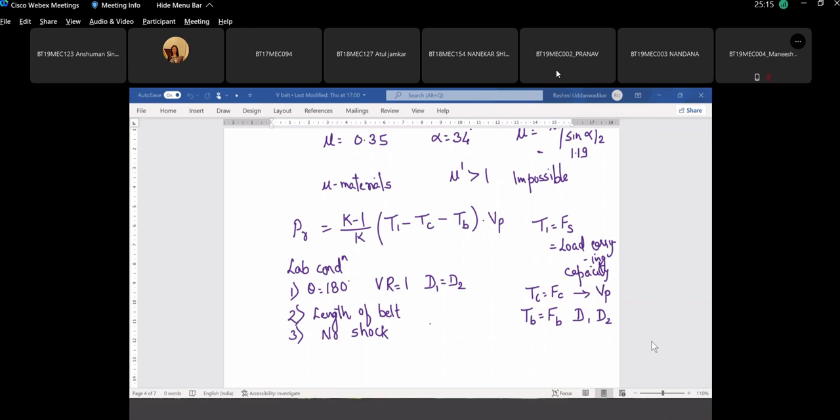Turn the page. What is the next table? Turn the page. What next? Transmitting capacity. So this is giving you from the first table for a given belt cross section how the value of power, rated power in kilowatt hour, that is calculated. So these formulas are given for a reference. We are not going to use these formulas, but this is only for you to understand how, using experiments in the laboratory, the power rating for a given cross section is calculated.